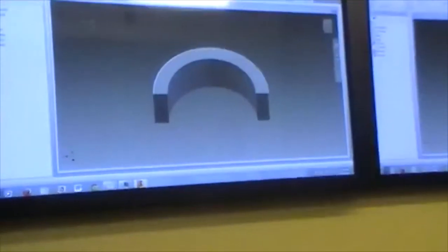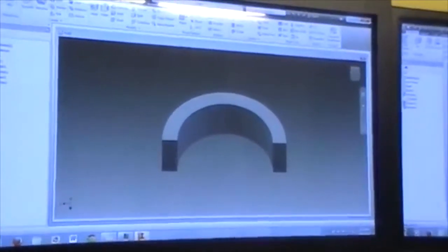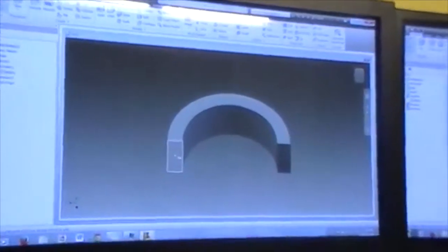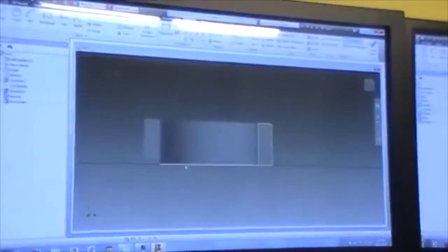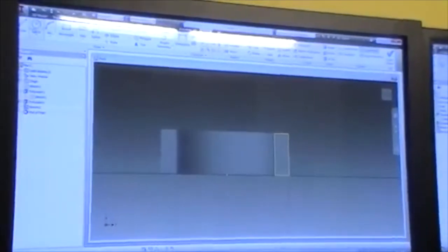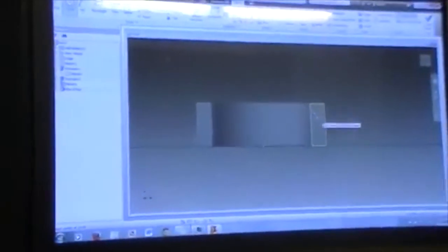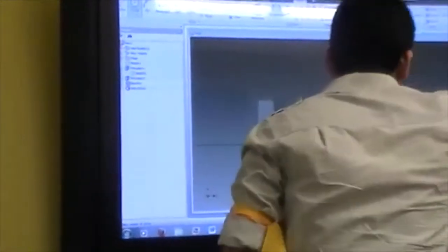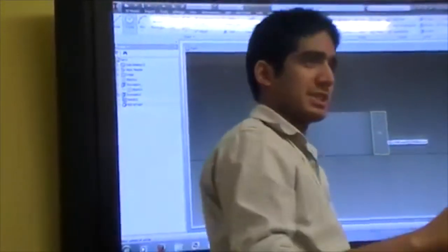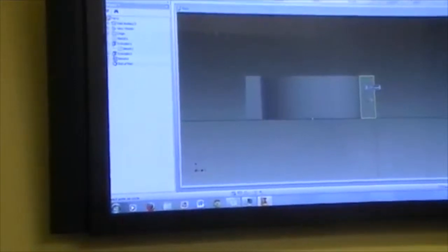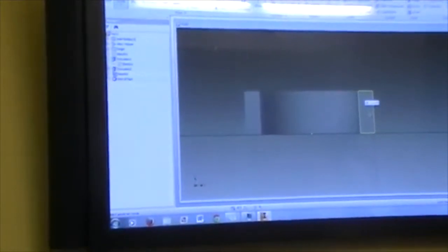So what we can do is create a 2D sketch. So we come here, and then I'm just going to go ahead and select this leg right here. Okay? And we want to bore holes, right? So I'm going to select a circle. And if you guys can see this, there's faint dotted lines. That's the snap-to feature that's showing, hey, you're at the center point of that geometry. So I'm going to go ahead and draw a circle. Let's make this 5 millimeters.